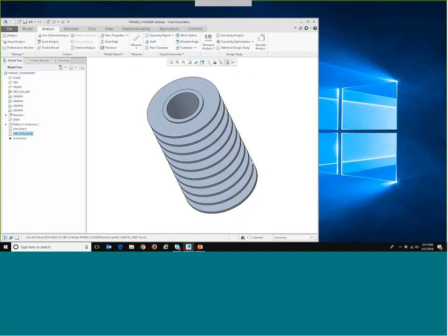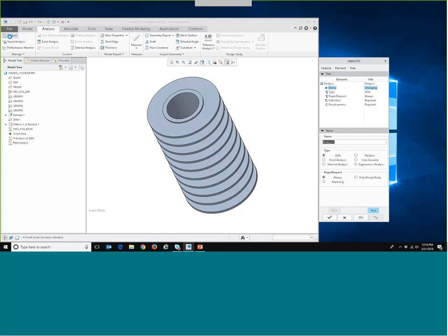So now what we'll do is we'll create our Excel analysis feature. And actually, I made one little mistake here. We want to put all the stuff before this efficiency analysis, so I'll just activate insert mode, and then we can insert everything above that efficiency relation analysis. So now we want to create our Excel analysis feature. So we click analysis, and for the name, we'll type in find efficiency.